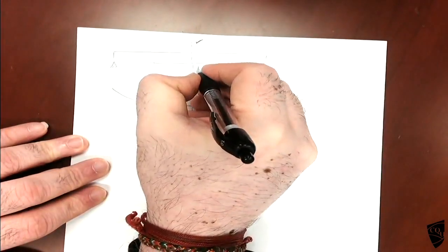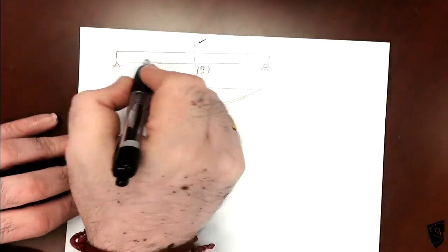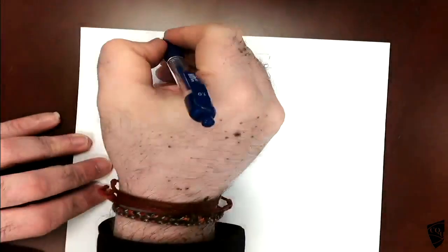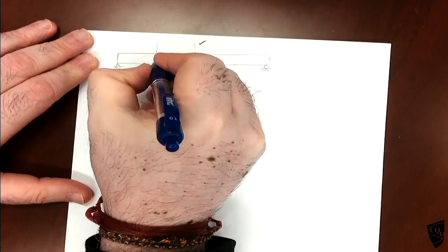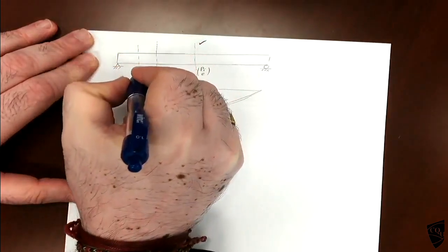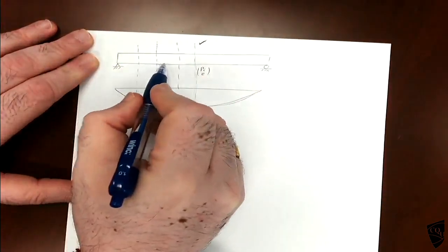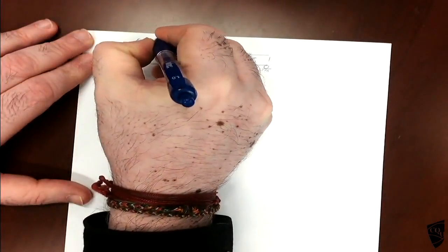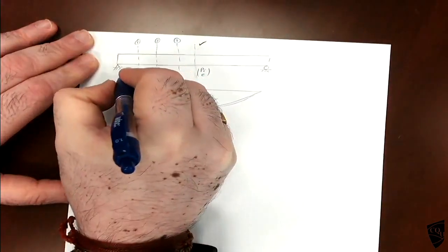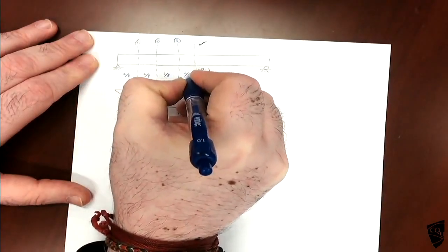So that one is Pi and eccentricity we already calculated using the Magnel diagram. So now we need to know the other places. So what we do is, rather than consider x distance, we divide this one into equal parts, say maybe 1, 2, 3 separate sections, so this one say L by 8, equal.